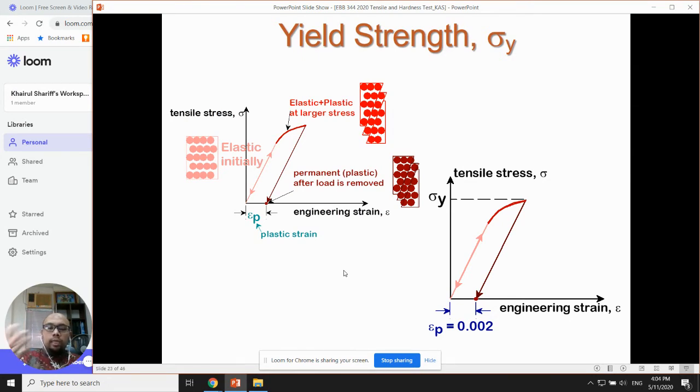When you convert into the stress-strain curve, it's easy when you talk about the elastic region, meaning that it's a reversible process: when you release the load, the atom arrangement can be positioned back into the original position. However, in contrast, when we talk about the plastic deformation of metal, the deformation remains as it is, or we call it a permanent deformation, and the atom layer arrangement shifts in the shear mode, because when you pull, the atoms slightly change their arrangement, maybe by a certain angle of degree.